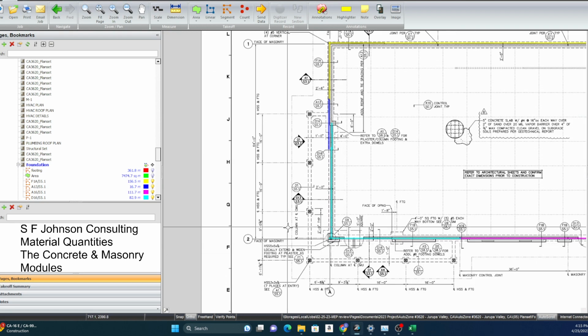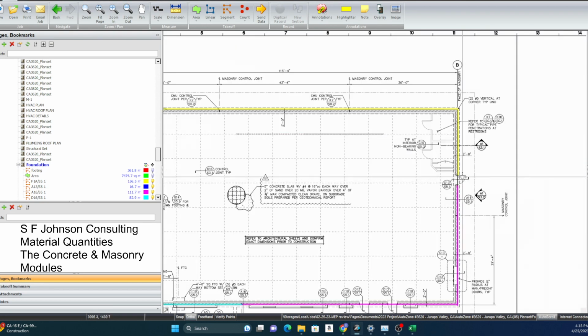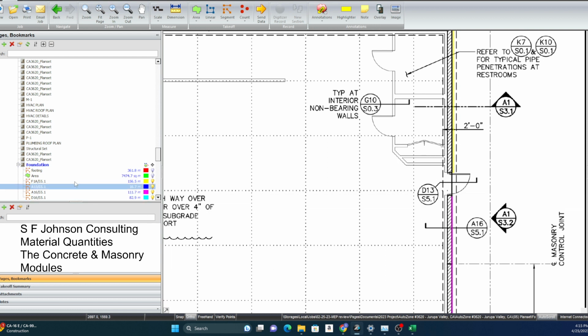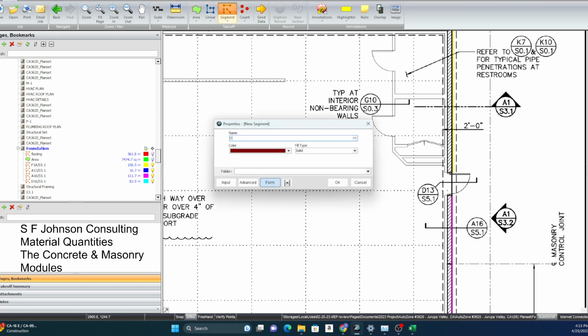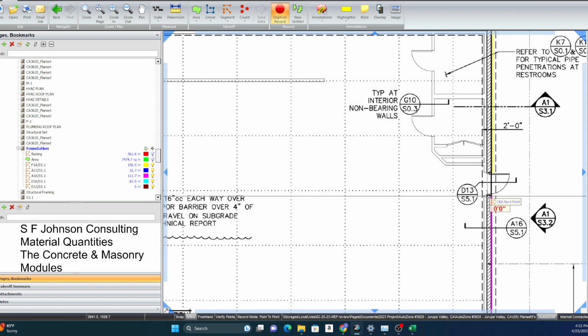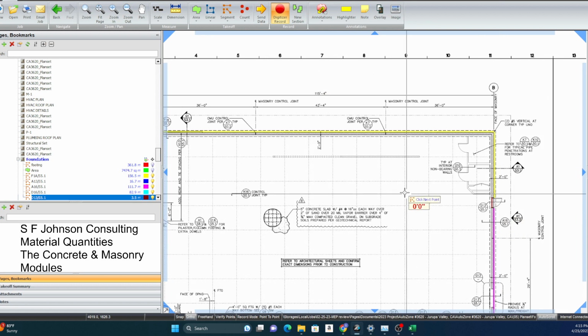All right. And so we're just gonna measure all at the doors because they're all the same. Maybe something we need. D13. Okay, so we already did slab on grade, cubic yards. I always do cubic feet divide by 27. That gives you cubic yards. All right, so I don't know that we'll need these, but that's what that is.